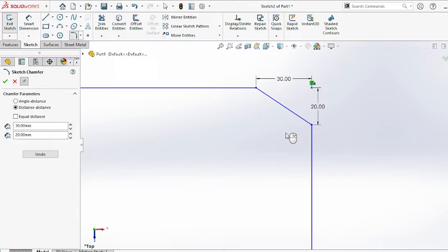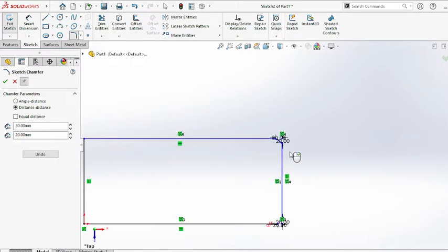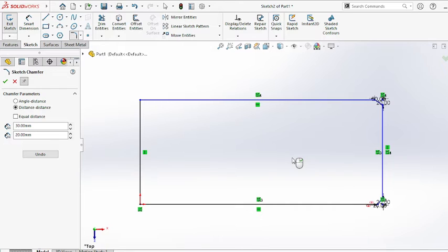Asymmetry means unequal distance. In asymmetry chamfer, you don't know how much angle is between here. Yes or no? Okay? Here also you don't know how much angle. But in symmetry chamfer, you can find out the angle is 45 degrees always. See, this is called asymmetry chamfer. This is called the distance method. In the distance method, what do I have to specify? Two distances, same or equal.